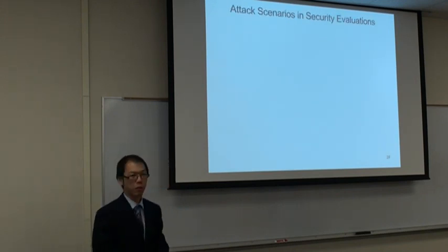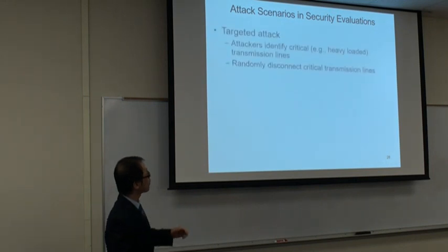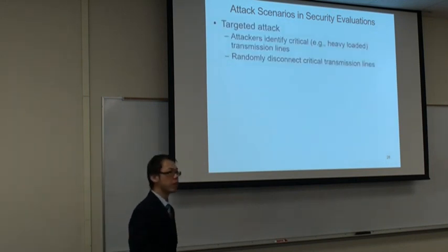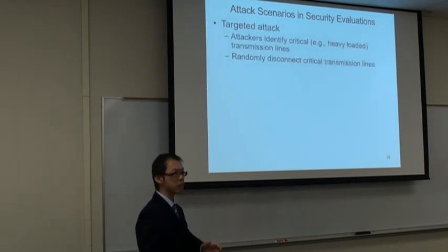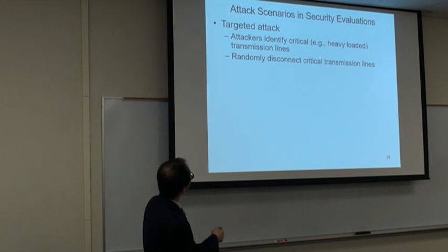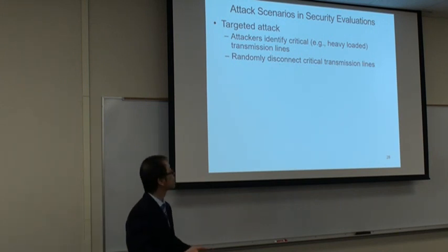So for the security evaluation, for example, I am thinking about very specific targeted attacks, which means the attacker has full knowledge of the system, usually an insider without protection, and can identify some of the critical transmission lines, such as the heavily loaded transmission lines.